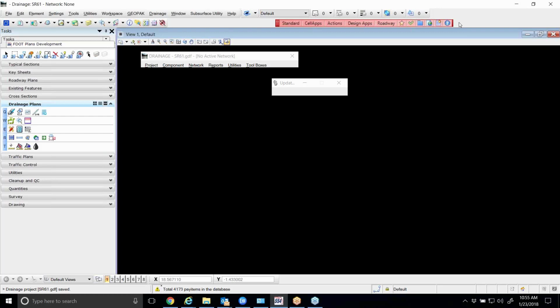We put in the station, the offset, the type, node ID, the reference surface. We'd put all this information in as needed. We're just going to do one node, which will be a curb inlet, and we're going to do the outlet. My thinking here is once you know how to put in a couple of nodes, if you can do one or two, we could do a couple of hundred. So we're not going to spend hours inside of this node tool here.